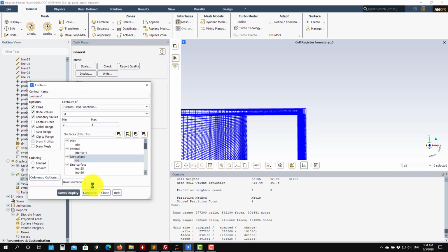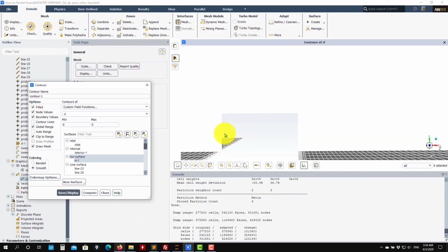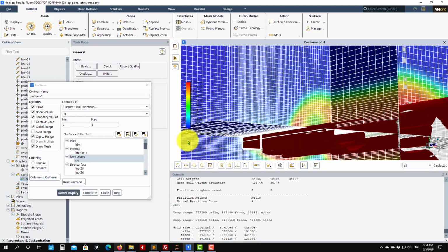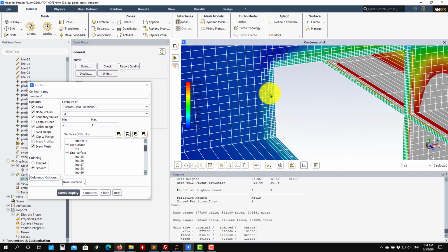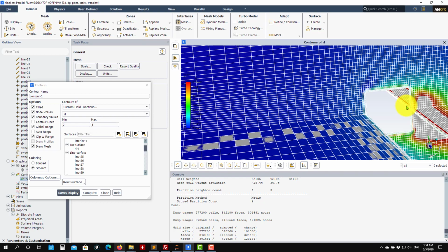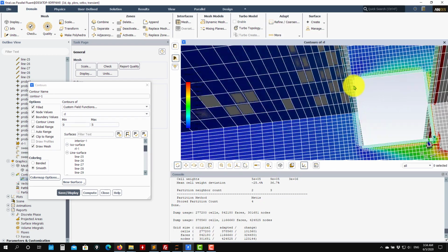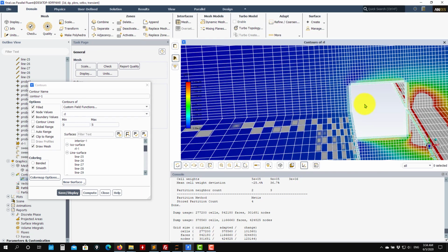Okay, if I go now here, draw mesh, and this, just to put a color there. Okay, and I don't want to see this. See what we have. Now this was refinement, and now surely this one will be my y plus average. Previously was about 19, now this will be below 10, I'm quite sure. Okay, in all that direction. So this is one way to do the refinement within Fluent.